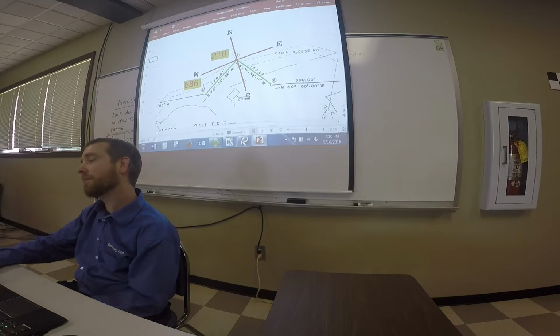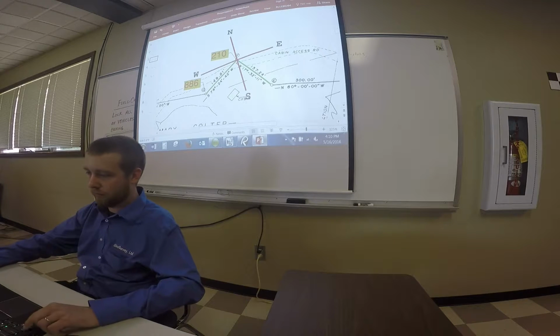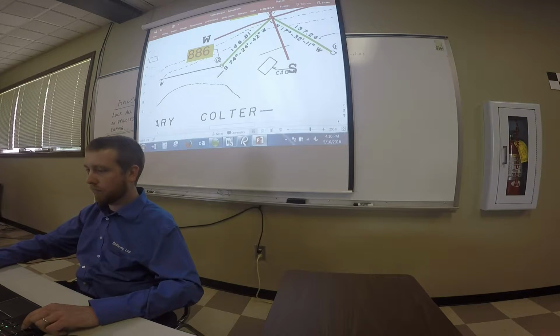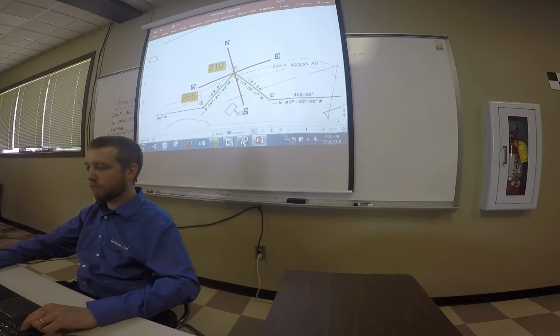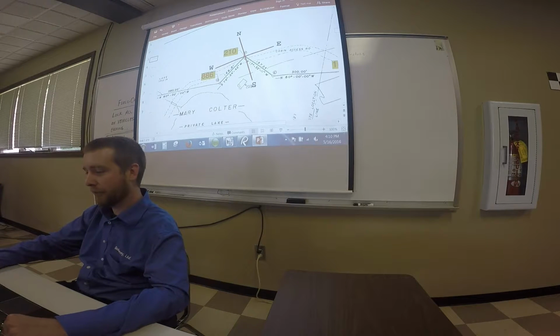John, I'll point out, unique to this plat, and a lot of surveyors do it, is it has direction indicators telling you what direction it's going. If you look right there, see those lines? Those are telling you what direction the bearing is going. Yeah, so on the original plat there was probably a little arrow right here pointing that it was going northwest this way, northeast that way, and it just got lost after it got copied so many times.